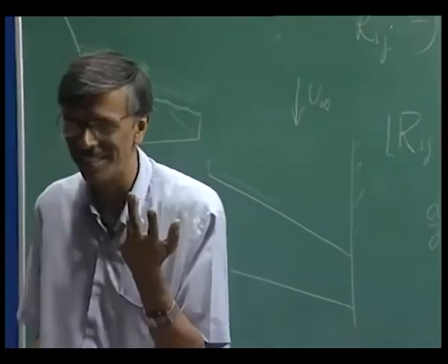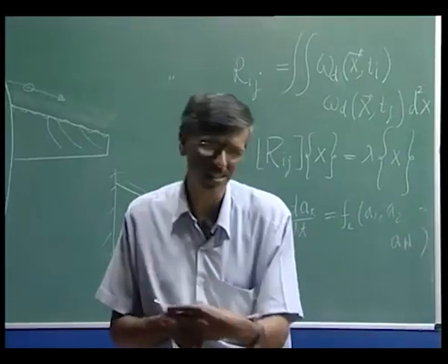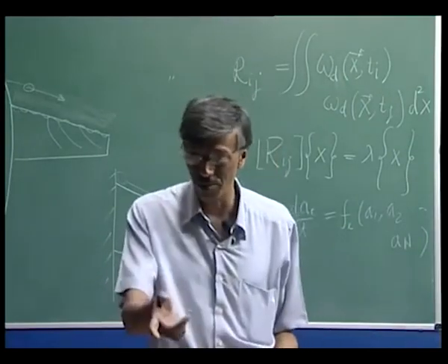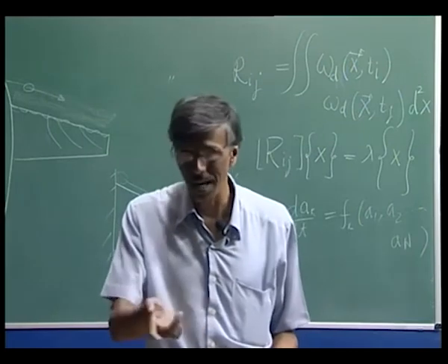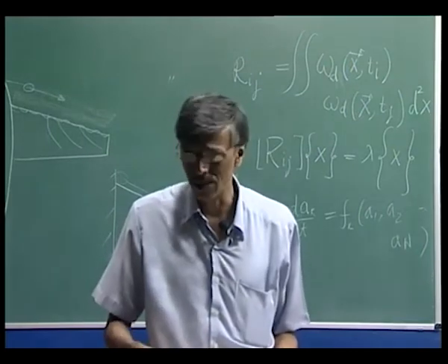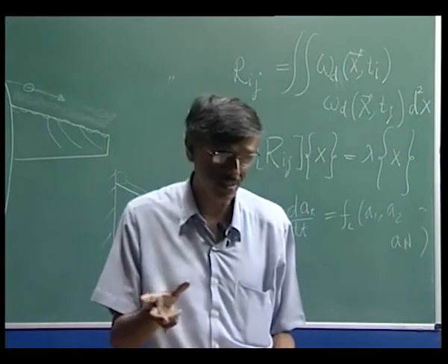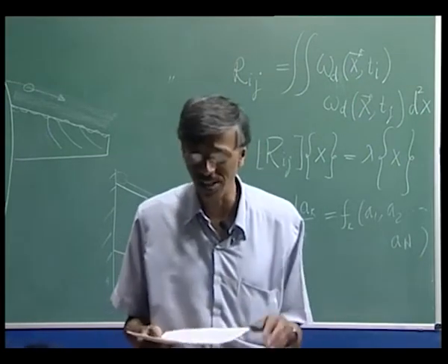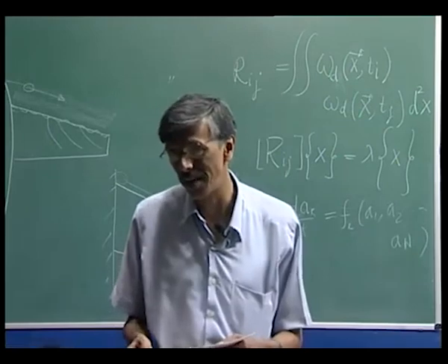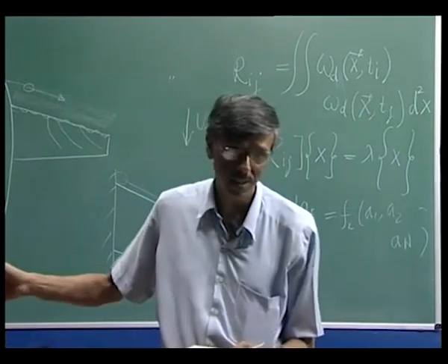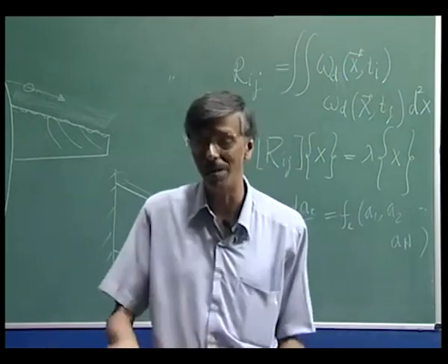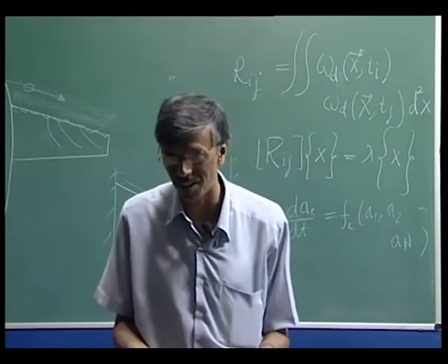But these days you can go to the tunnel and refine the wing body junction in a much clearer way. That is one of the stories behind all NLF wings. They spend time designing that wing, and in the last stages they do this wing body junction design in a very careful manner, so that your section properties are good, your wing properties are good, but you still do not suffer from leading edge contamination.